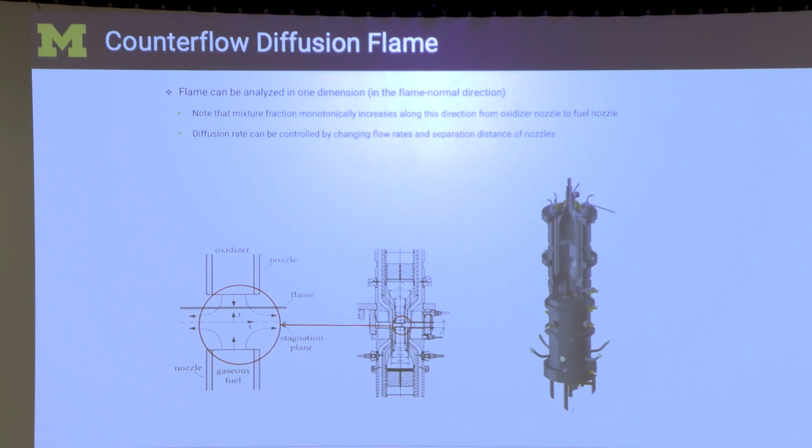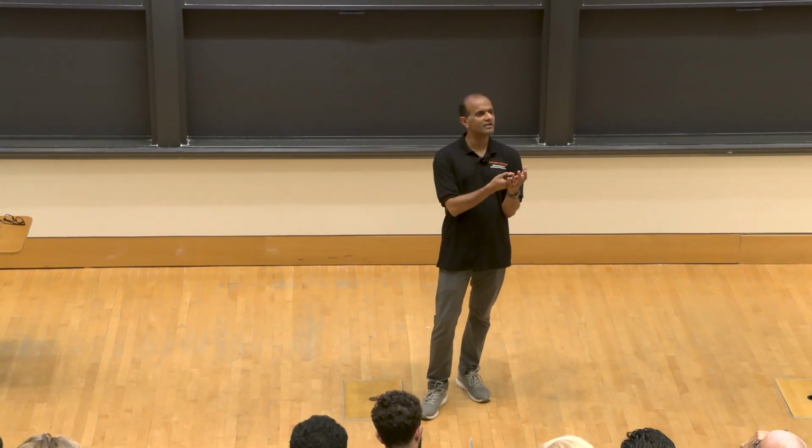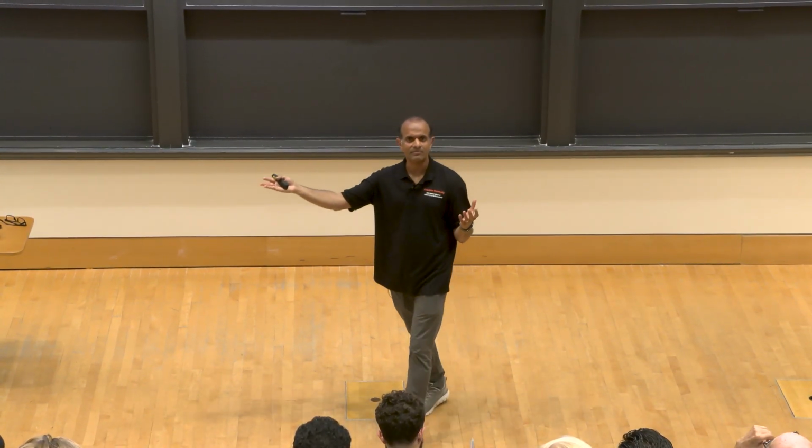What we do is we take some canonical flow that we are able to measure or study very easily using one-dimensional simulations, let's say. And we say the practical application that we have, let's say aircraft engines or jet flames or whatever it might be, has a similar flame structure to this canonical flame. So if you have to do this kind of manifold-based method, you first have to identify an equivalent canonical flame, which has some characteristics that are similar to your final application, okay?